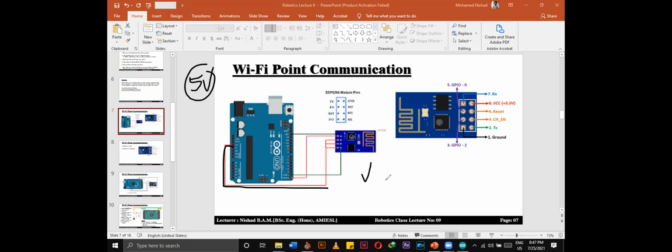VCC terminal, right? Other than VCC, we also have to give power to the enable pin, that means the ENA pin or enable pin. Because VCC means we just turn on this device, and we connect ground to ground, so we power up the device.